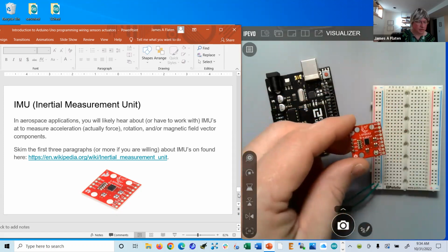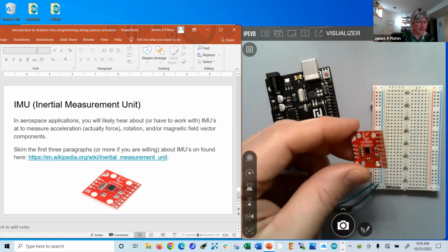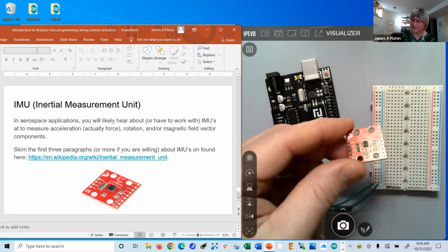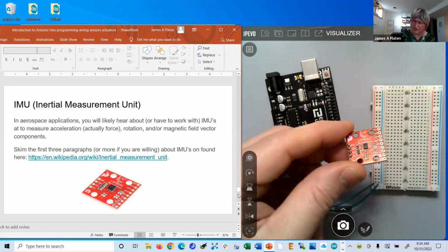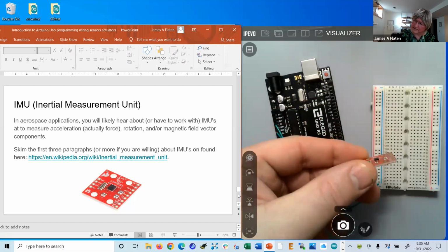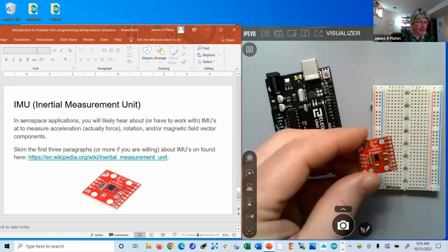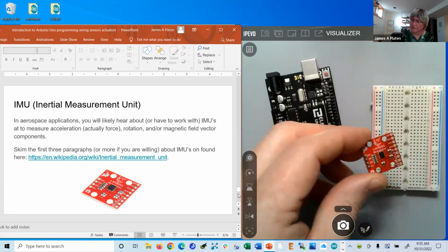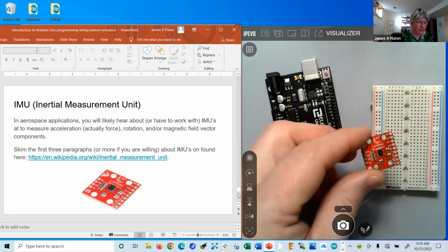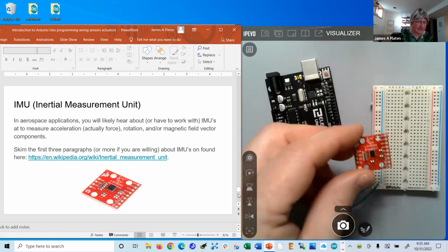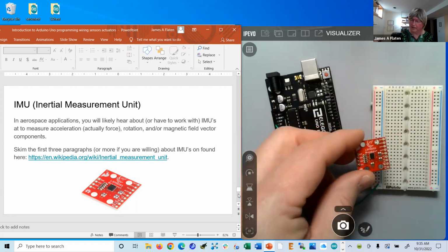This particular measurement unit measures force, and so you can use that as a tip sensor because it can sort of notice the gravitational force, and either that's in this axis direction, or this axis direction, or this axis direction, etc. And it also measures rotation, so it's got 3-axis gyro, and it also gives 3-axis magnetometer. So this is called a 9-degree of freedom inertial measurement unit.